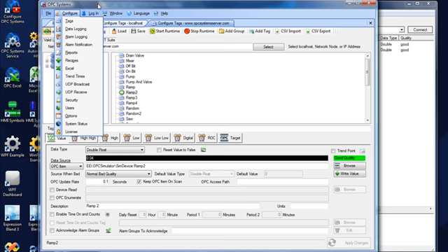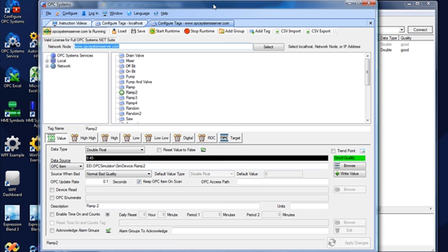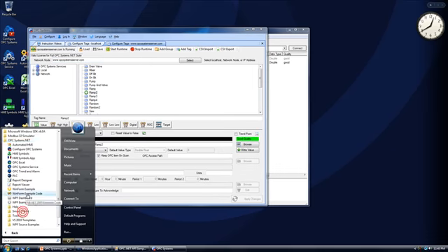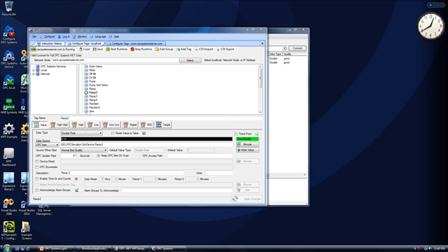So we can use this technique to define to a remote network node name with all of the configuration attributes. That would include data logging, alarm notification, reports, recipes, the UDP broadcast feature, security configurations. Those can all be done remotely from your OPC Systems Configure application. You can also use the free-to-use programmatic interface to define all of these configurations from a .NET application that also supports remote connectivity. We can see an example of that under the WinForm example code, and I'm going to bring that up so you can see where you would define that remote network node name to connect to using the OPC Systems component.